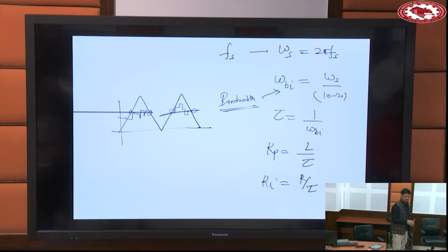Otherwise, if you reduce the frequency, the same synchronous machine will start rotating. You will not need any additional damper winding or anything. That is a special type of starting method. Because now you have made it compatible, within its limits, so that it can follow.